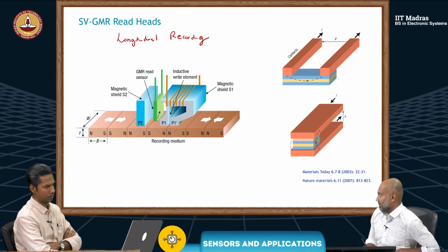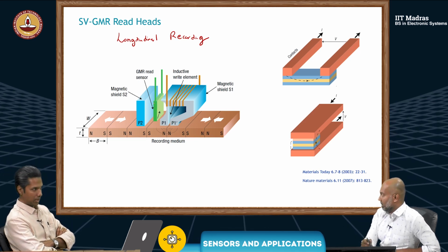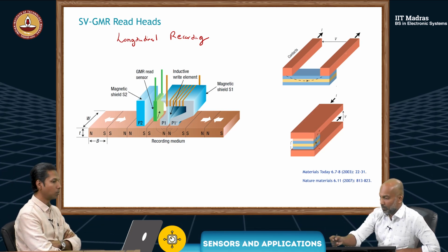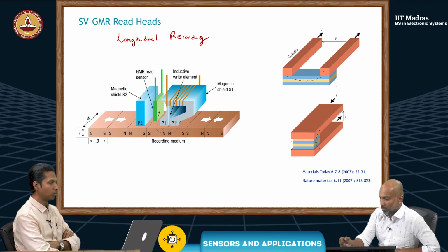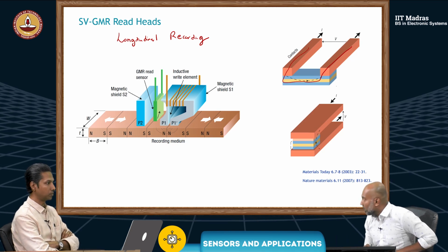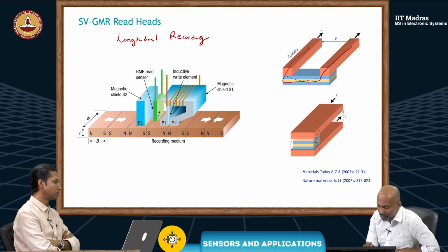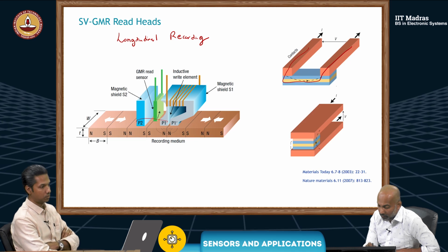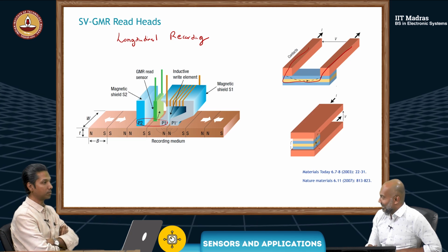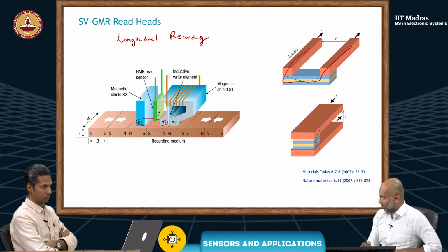But there's a catch here. You see our magnetic sensor here, the GMR. And we talked about how we have two contacts that provide the current to the GMR. So the current actually goes through here and comes out here, in plane. But when you have something like this, what you're going to do is limit the distance you can have between P2 and P1. Because if you put this one here, it cannot be smaller than that, because the current has to go this way.